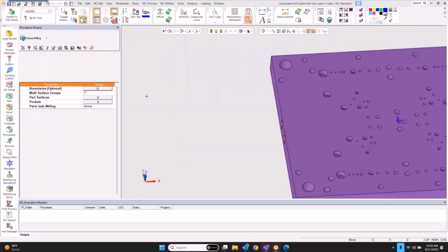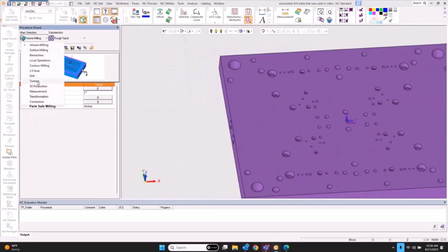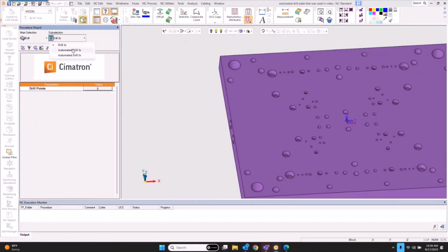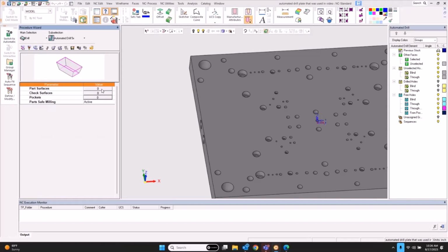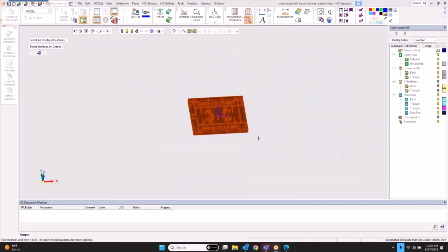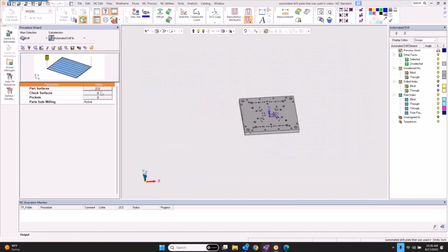Yeah, the gun drilling is very impressive with all the new drilling tools, and how you have to control it with the pilot and full force, and then the cross holes, whether they're drilled or not. Slow down, speed up, reverse, stop the spindle, reverse the spindle, and pull out.